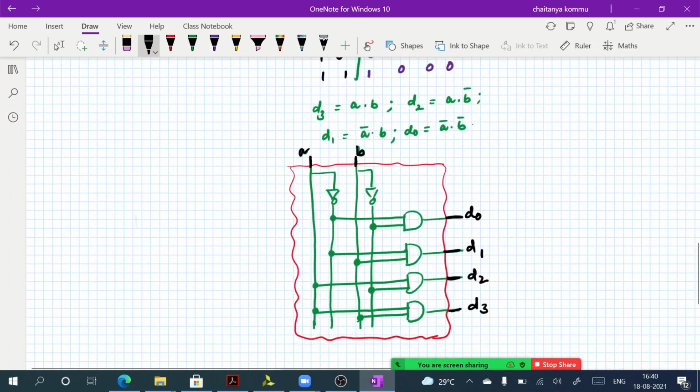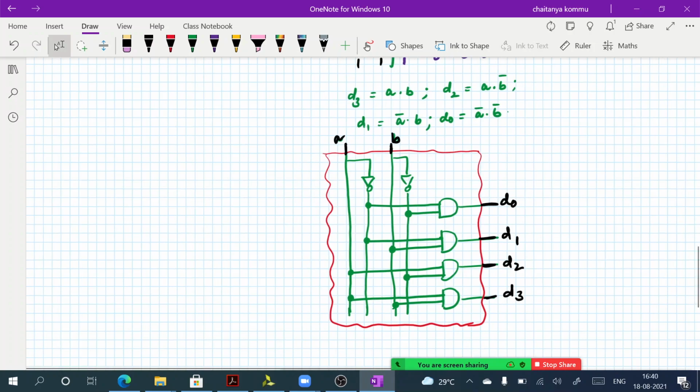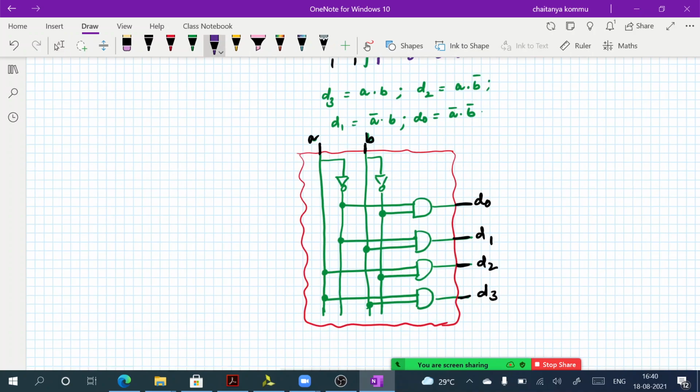So once we have a gate level circuit, it is possible to write the gate level modeling, right? Let us write the gate level modeling for this. Let us write module decoder underscore 2x4. We should not give a space; if you want to give a space, better to write an underscore. It is not necessary to write a capital D, small d also we can write. But the name should start with an alphabet, not with a number. Please remember this point.